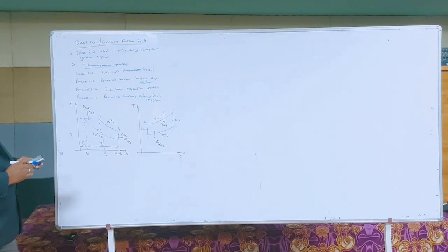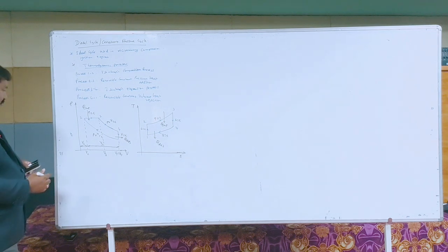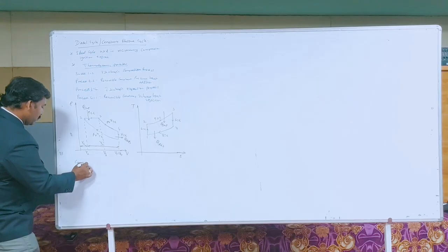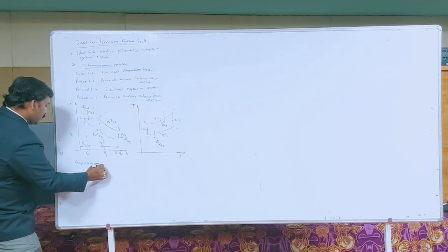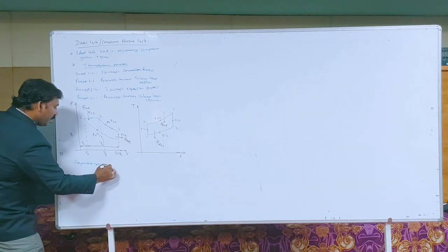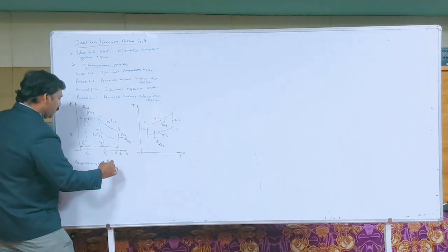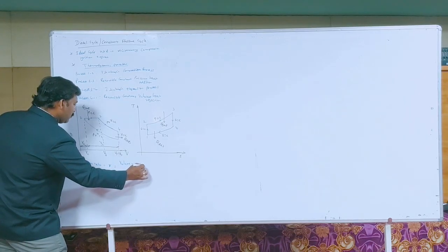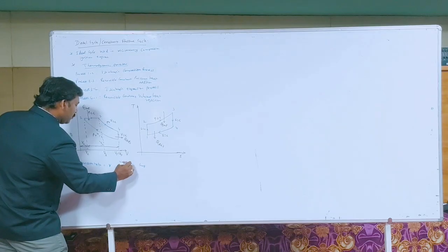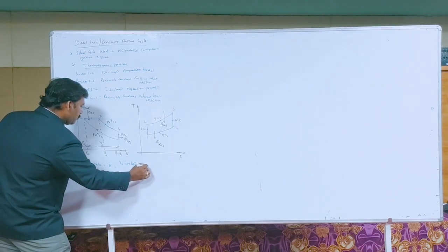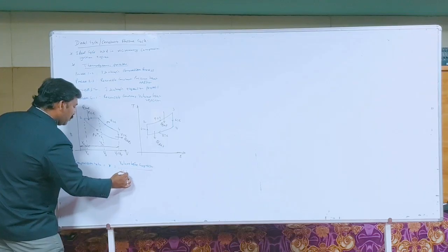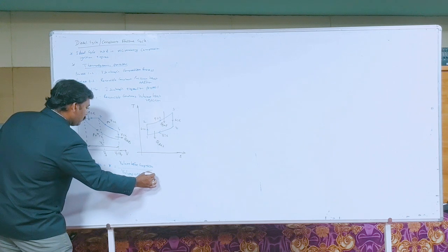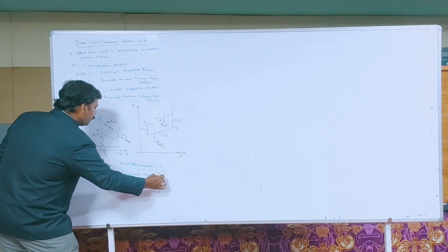Now, in this PV diagram, there are certain ratios to be remembered. Let us start with the first one, the compression ratio, which is denoted using the letter r, defined as the volume before compression to the volume after compression. So that is equal to V1 by V2.